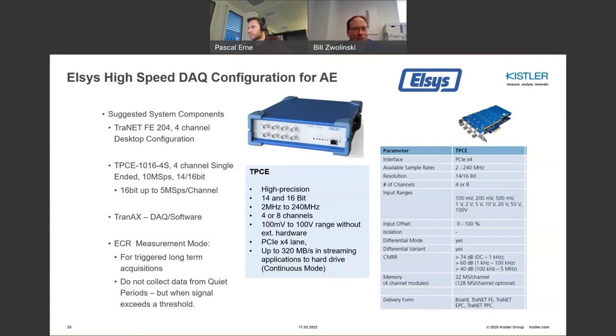Because data acquisition systems can have dynamic ranges of over 100 dB. And having any sensor, I don't care what type of measurand, that has 100 dB dynamic range is really a special sensor. So keep in mind that nowadays there's such a wide choice of data acquisition. And certainly it's always good to find your favorite application engineer when you're trying to figure out what to use, because the devil's in the detail when it comes to data acquisition.